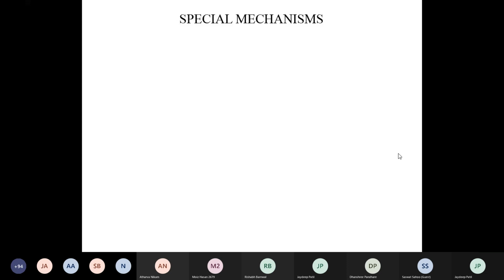When this concentric circular arc is the contact between the wheel and road surface, then you will get the pure rolling motion, and it prevents the skidding of the vehicle. If we look at the tire of, suppose, a two-wheeler, it is a circular arc, not a flat. Why is it a circular arc? Because to prevent the skidding of the vehicle, the contact between the wheel and road surface is a concentric circular arc.